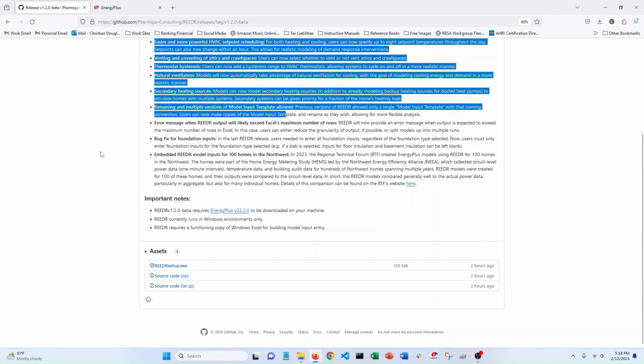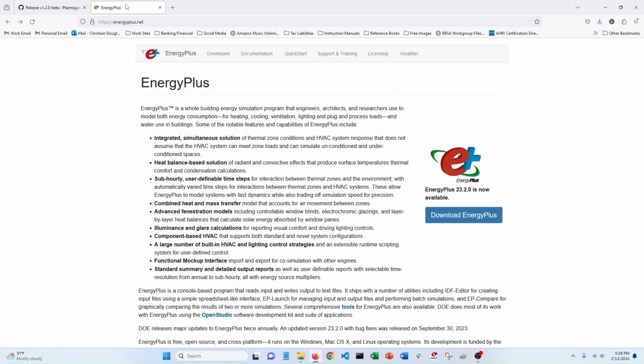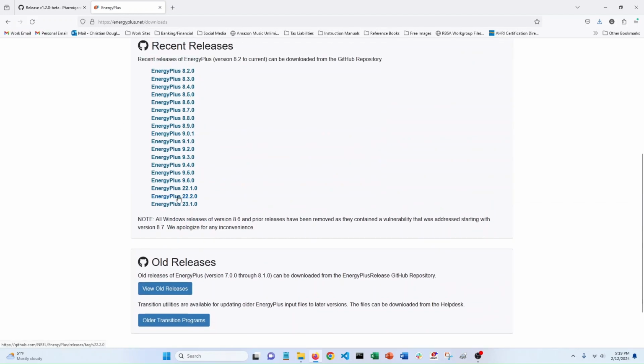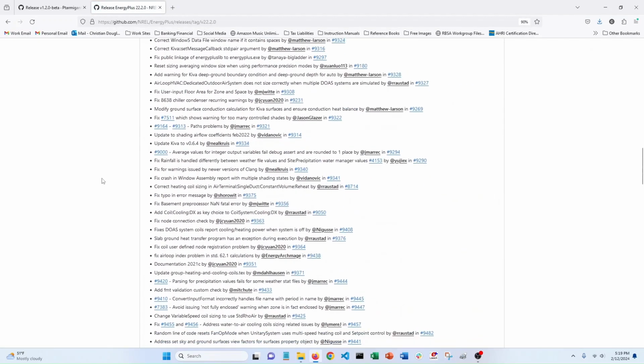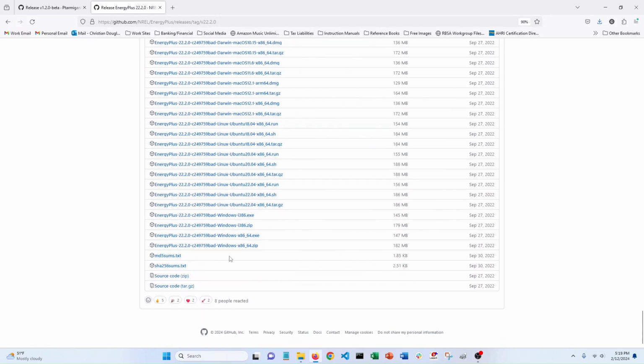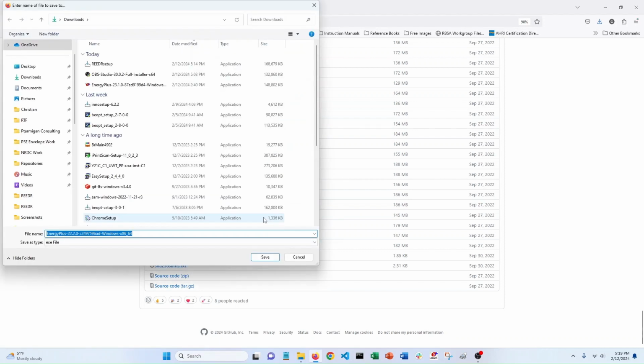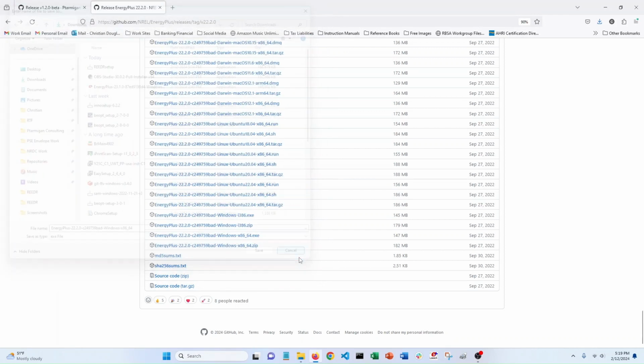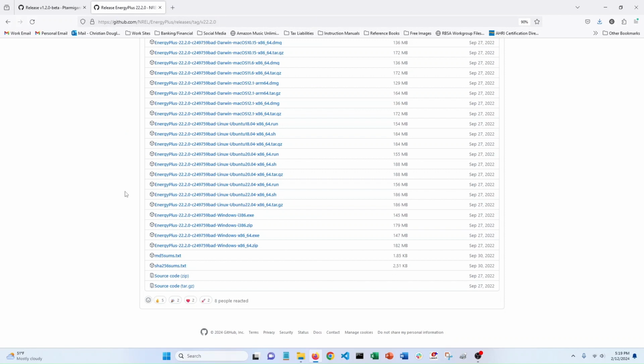The other thing that you need to do, and again, I will include this link in the video notes, but you need EnergyPlus on your computer as well. And specifically, you need EnergyPlus version 22.2. So this version right here. And so if you have a Windows computer, 64-bit machine, the version that you would want is this x86_64.exe. So if you click on this and download that file on your computer, that will basically be an EnergyPlus Windows installer, kind of your typical thing that you just walk through and install EnergyPlus on your machine.